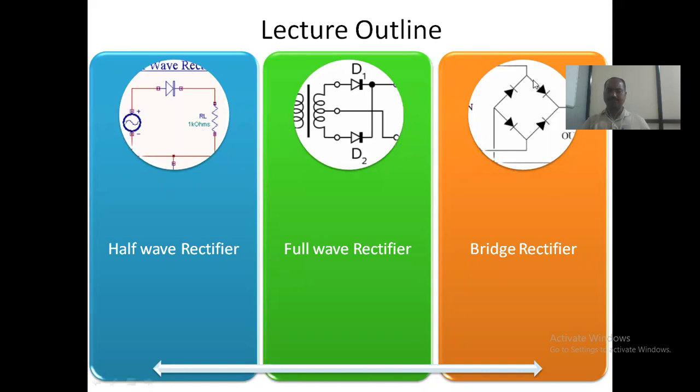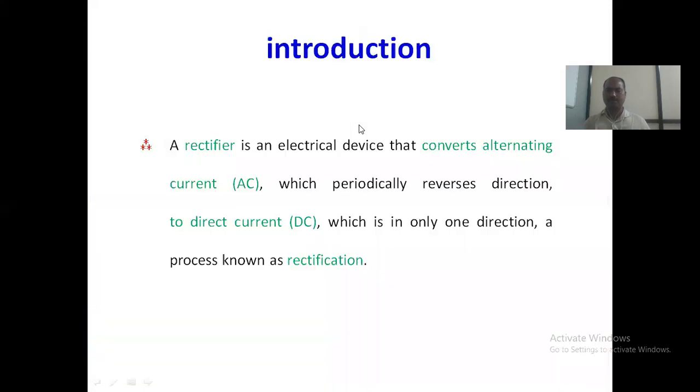These are the two inputs applied across it. We have seen the details in a previous session. In the bridge type configuration, we use 4 diodes, and at a time, whether in the positive half cycle or the negative half cycle, 2 diodes work at a time, one for the upper and the other for the lower. That's why the output coming across it is less noisy than that of the center type configuration. Okay, that is the outline of this lecture.